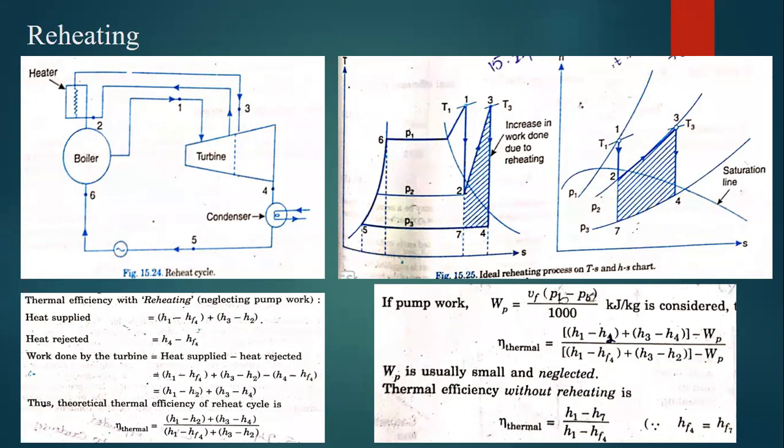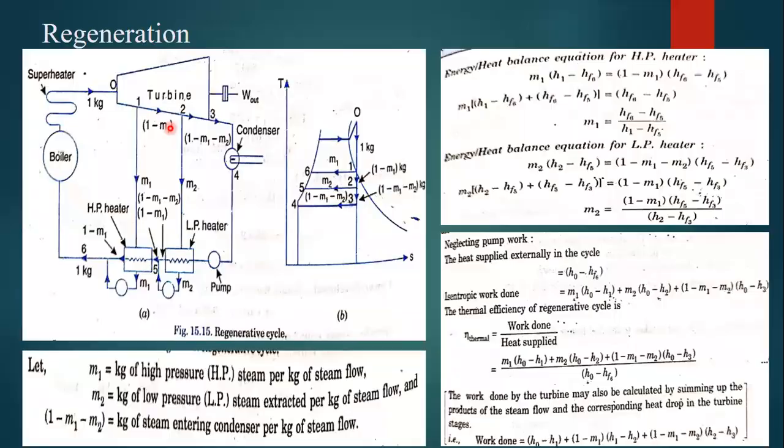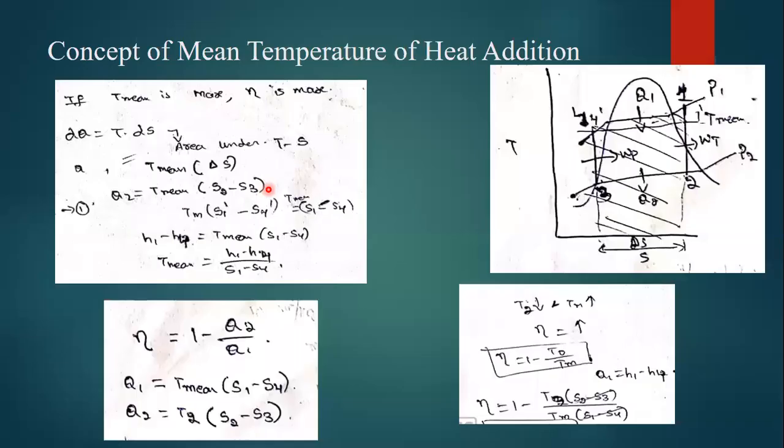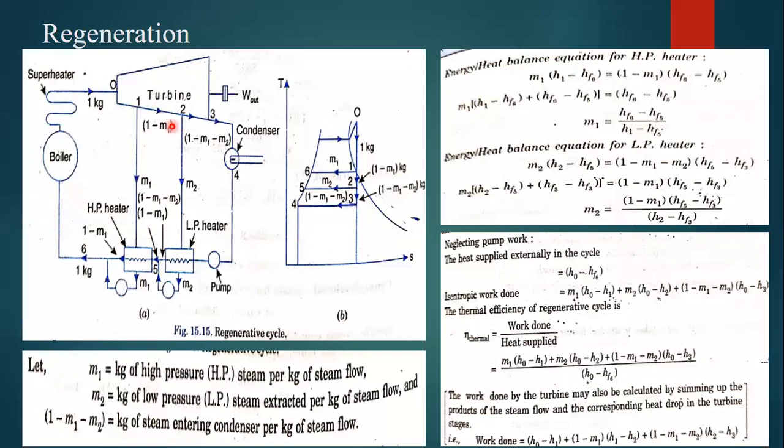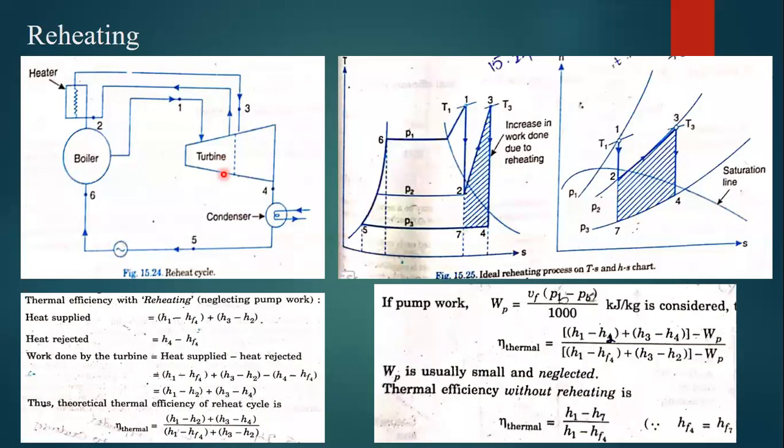Okay, in reheating, what we are going to do is, after some expansion, the whole steam is extracted here. In regeneration we extracted some of the steam to heat the feed heaters, but here, after certain expansion, the whole steam is taken.